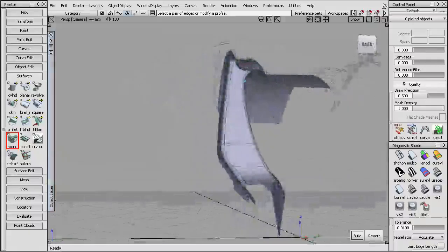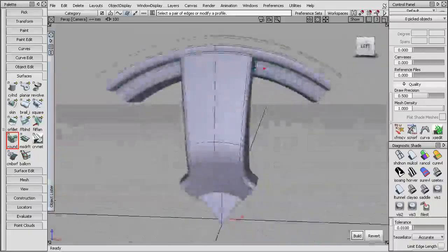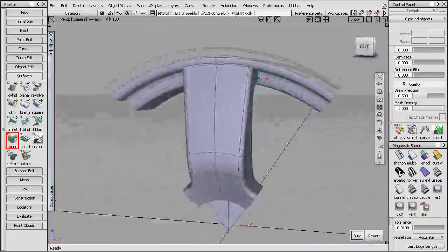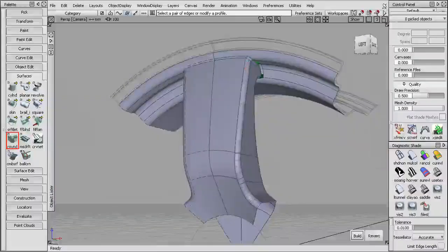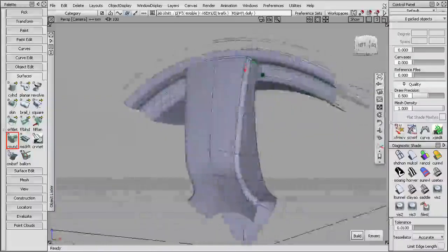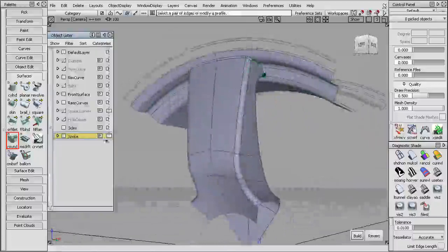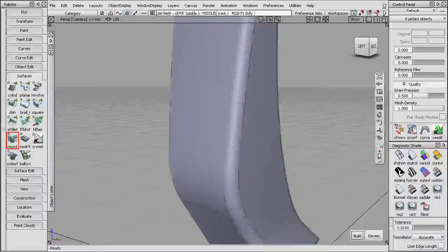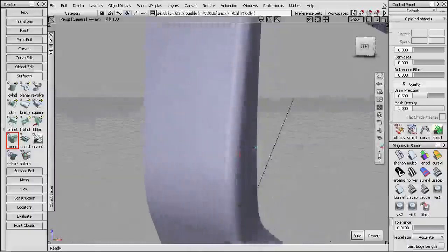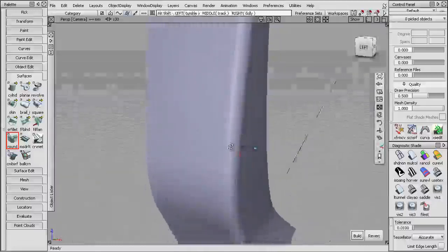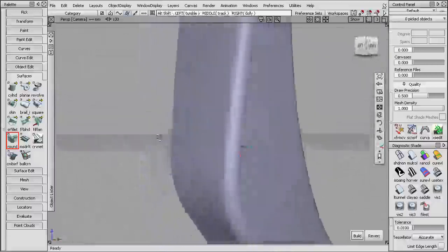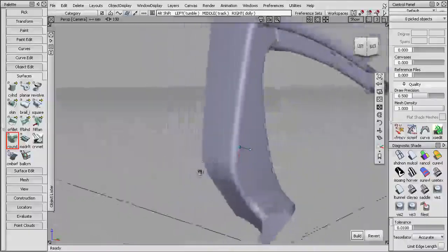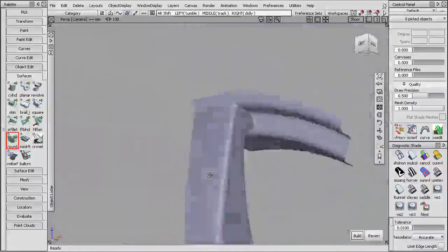So here I've intersected and trimmed all the surfaces to create the main spoke shape, and I've also applied a fillet to the edges using the round tool. Now the round tool is limited to G1 tangent continuity, which means that if I toggle off the model, you can see that the highlight is quite distinct when it goes from the circular round onto the flat edge. So it's smooth to the touch, but visually it's a bit crude.